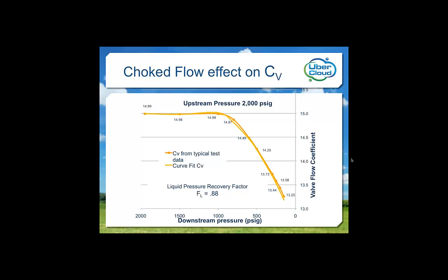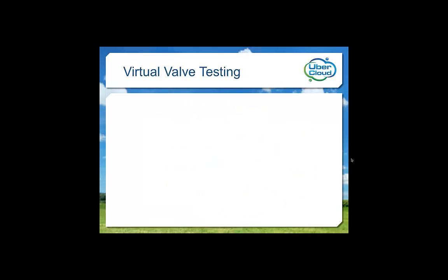So, the challenge for controlling in the transition region is typically avoided by limiting the pressure drop. For the typical control valve with F sub L of 0.88, pressure drop is limited to half the upstream pressure. Therefore, for severe service applications with very high pressure drop, the system designer seeks a valve with F sub L above 0.95, which defines a small transition region and a wide range of control. My objective with this project is to develop such a severe service control valve.